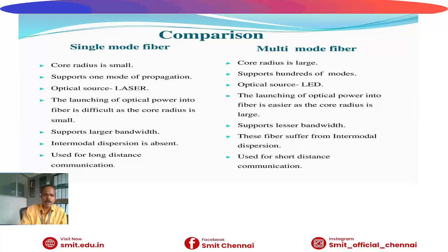Single mode fiber is used with a laser source, though launching power into the optical fiber is difficult. It supports a large bandwidth. Here intermodal dispersion is not at all there. It is particularly meant for long distance communication.